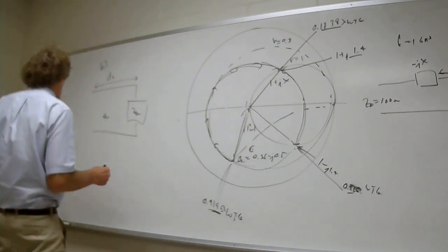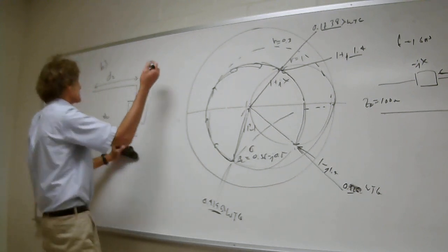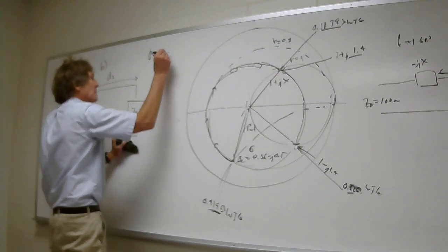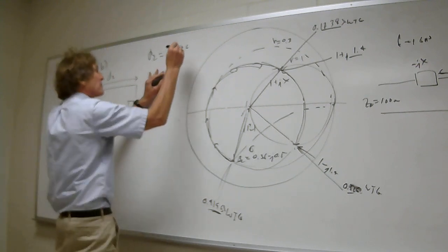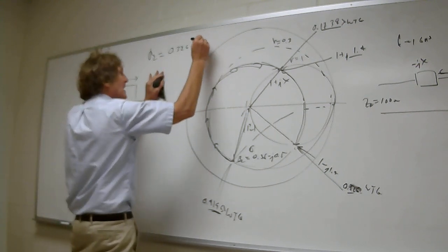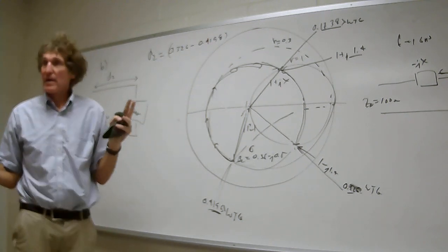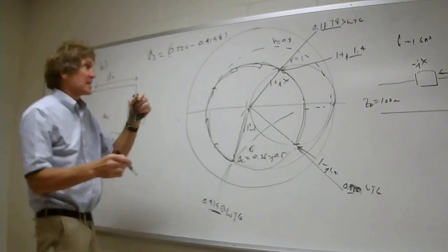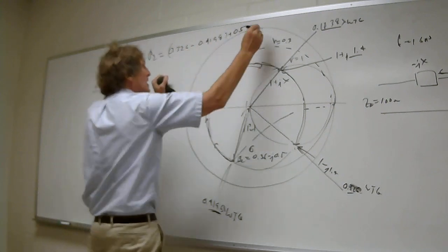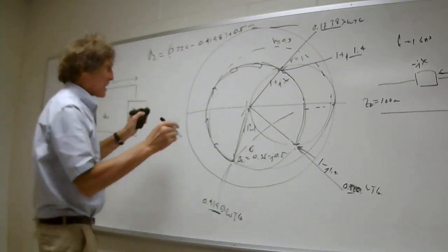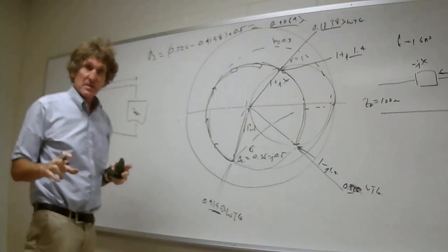Okay, let's go. So I'm going to move how far? I ended up at 0.326, right? This is going to be D2. I ended up at 0.326. That's the mile marker I ended on. I have to subtract this from it. 0.4198, right? And that's negative. Do you agree with that? So I have to add a half wave because it's negative. So then I add 0.5 to it. And what do you get? And this will be in terms of wavelength. 0.4064 lambda. Agree? Because it is in terms of wavelength.